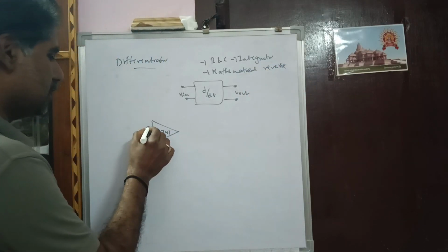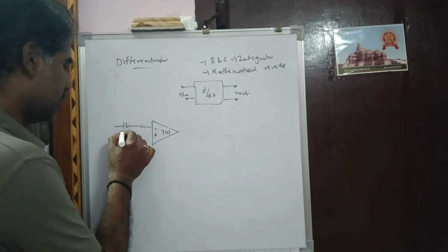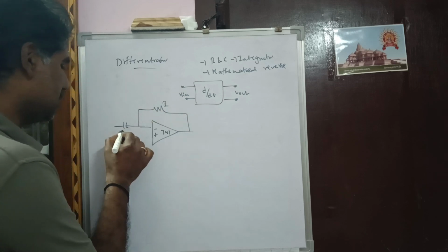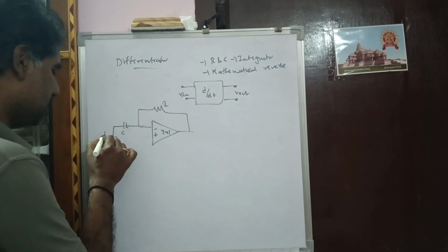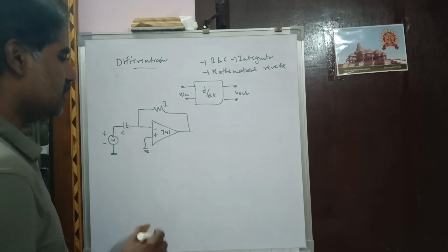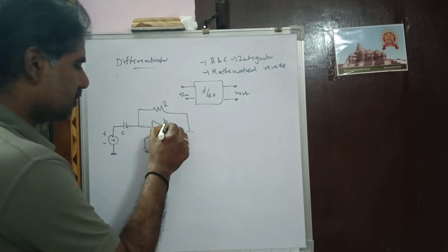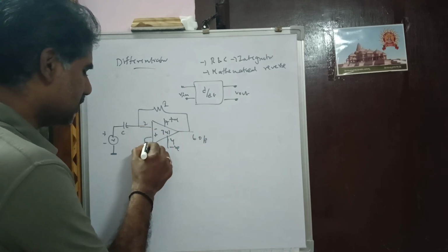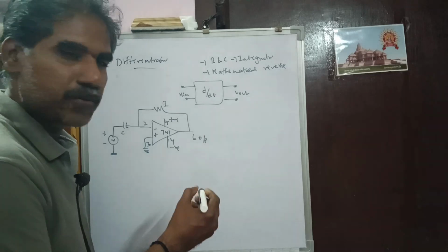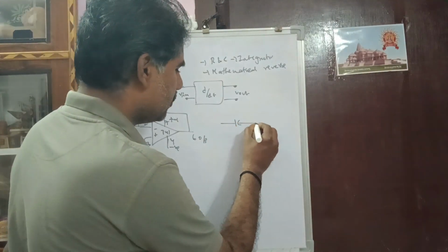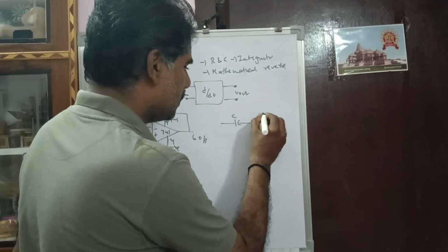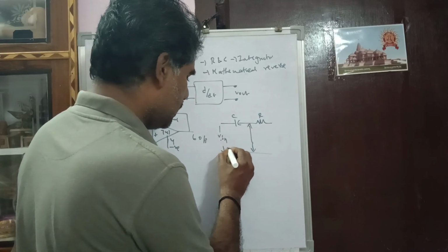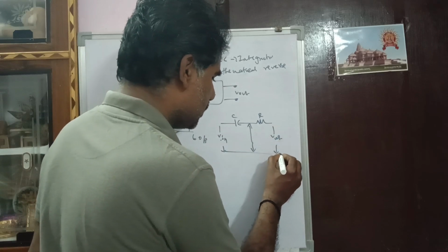Another thing is I am taking the capacitor over here, simply placing the resistor over here as feedback, and applying an AC signal, and the non-inverting terminal is grounded. Again, 7th pin positive bias, 4th pin negative bias, 6th pin output, and 2 and 3 as inputs. Again I am redrawing this circuit with virtual ground, applying input Vin and measuring the output at V naught.